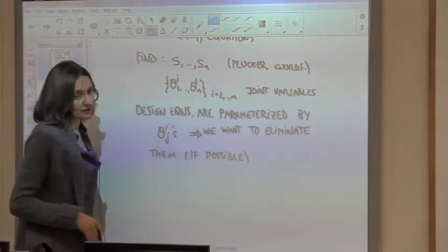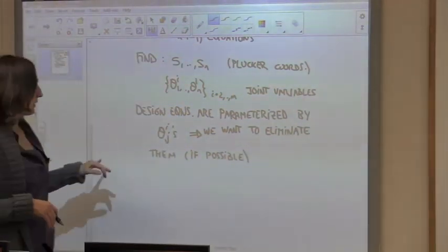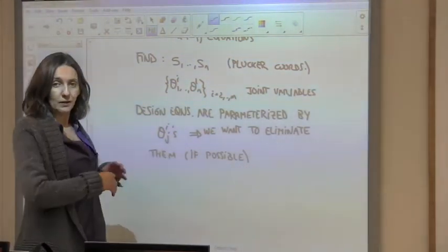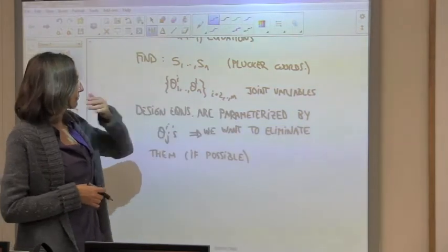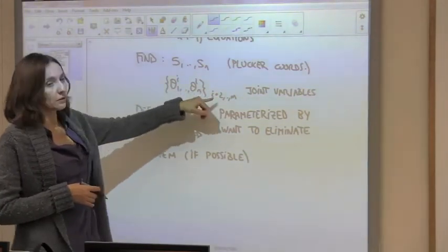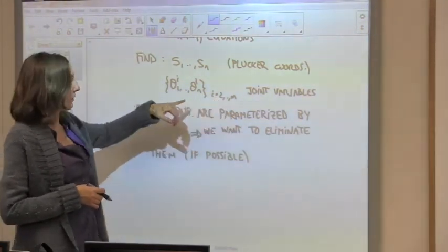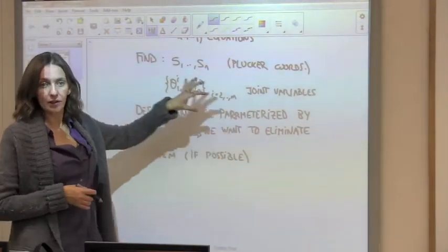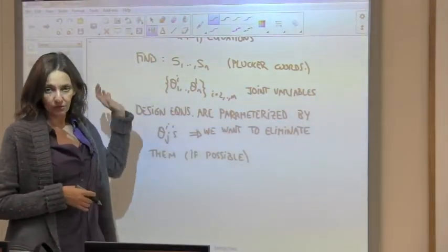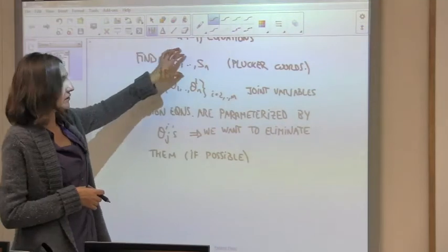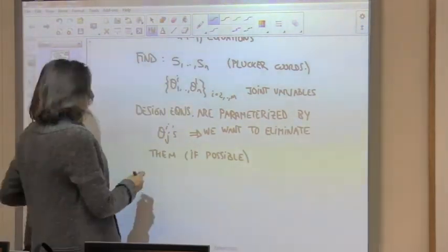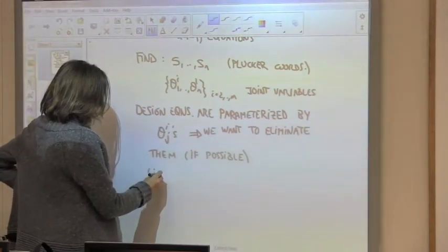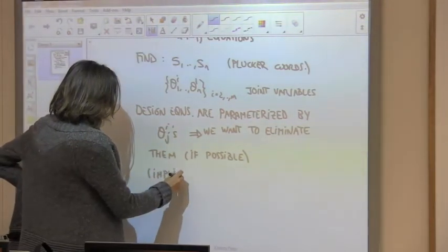But this is one of the things that, using Gröbner bases, we may be able to eliminate out of all this list of variables. Imagine if you have a 3-jointed robot with 5 positions. Here you have 3 times 5, 15 extra variables. You may want to eliminate those and keep just the structural variables in your equations. We can call that implicitization.